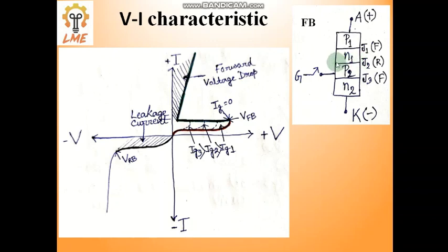In this case, current cannot flow because junction 2 is in reverse bias, which means the dielectric strength of this junction 2 still holds. The polarity difference between anode and cathode creates a pressure on this particular junction J2. They will not create any pressure on junction 1 and junction 3 because they are forward biased. Total pressure comes to junction 2. That is why current cannot flow.